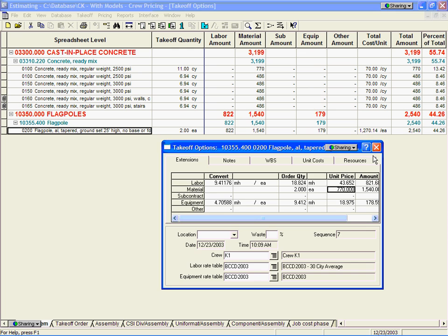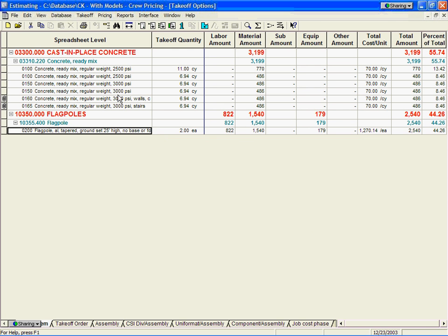Now, once we do take off items up here, if by chance you've got an equipment tab or you want to take off the complete footing of a building and so forth, there are more than one item that we would take off to do that. So instead of just taking off items one by one by one, what we did is we built construction methodology on top of the RSMeans item. Right now, if you took your RSMeans book and said, I want to use this number for budgets, you would have to take items one by one out of that book. What we did is we took all of those items and we grouped those in common tasks. We call those assemblies.